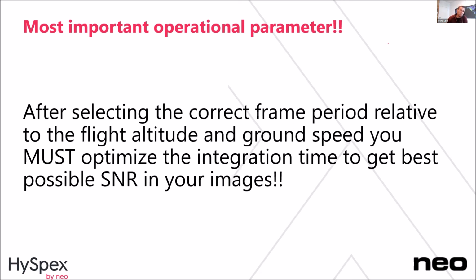it's important that you increase the exposure time until you saturate on your scene of interest, and then I would say decrease it by 15%. Then you're close to saturation, but you're not reaching it. Then you will have the optimal SNR in your images. And if you're flying for 8 hours, starting at 10 o'clock or starting at 8 o'clock, this has to be adjusted according to the sun angle during the day, right? When the light intensity changes.